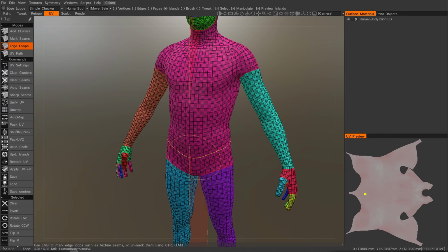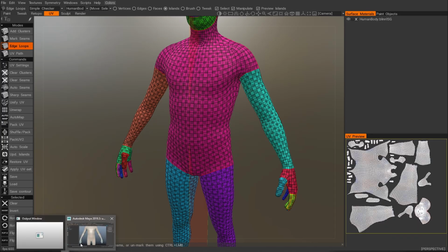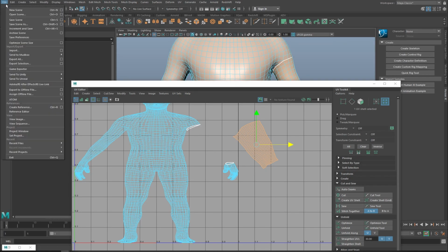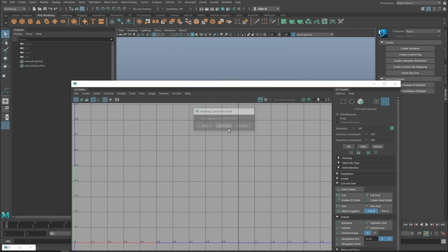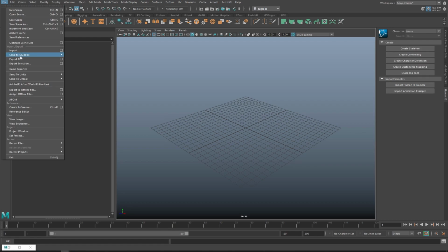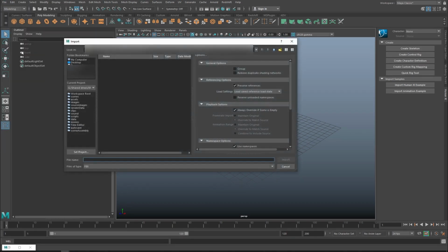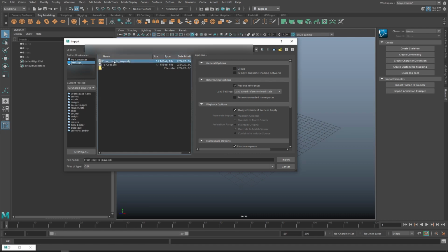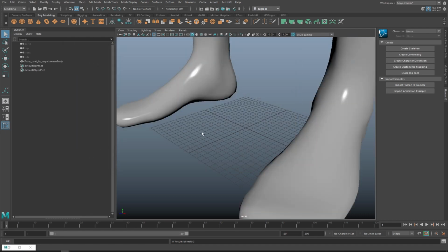Okay, now if I go back to Maya, I'll just open a new scene file, new scene. Okay, so now I can actually go and import this model. So I'll just go on desktop, and don't get confused, this is set to import an FBX file, but actually my file has the OBJ extension. And now you can see from 3D-Coat to Maya, and I'll just import this one.